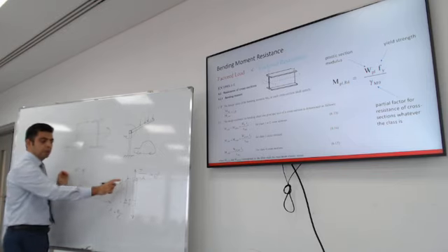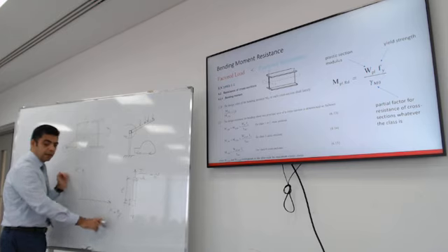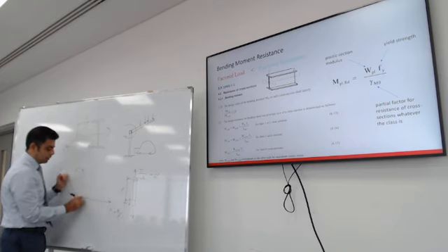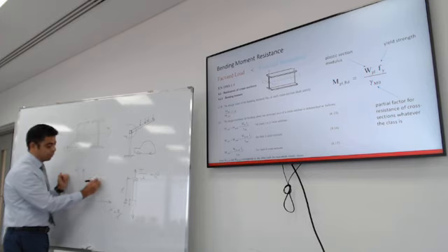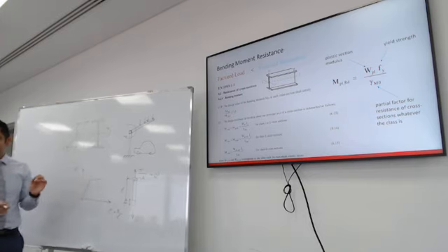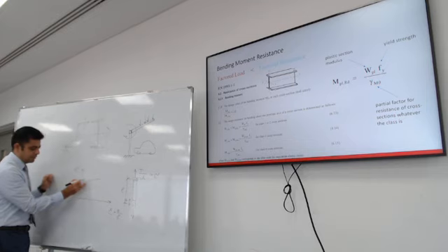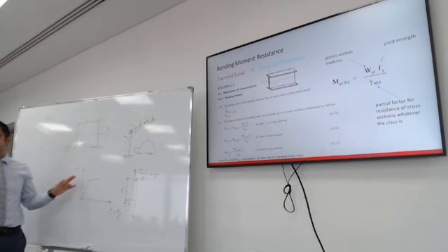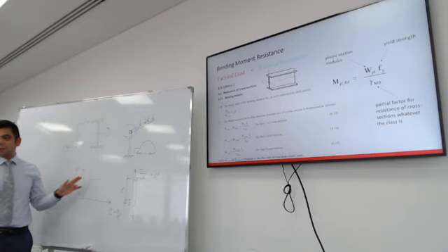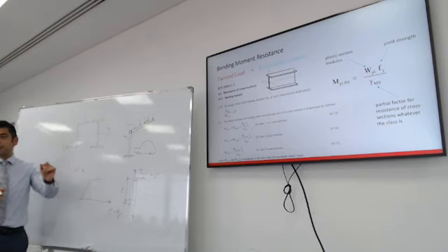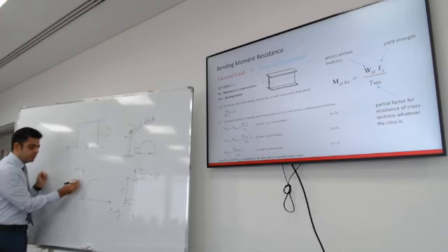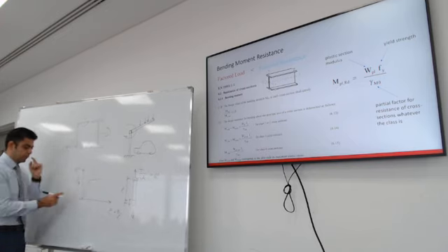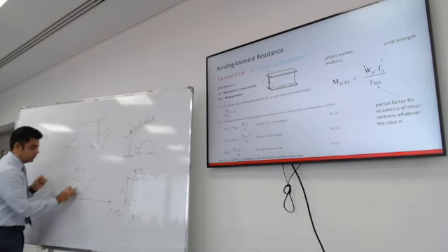The relationship between stress on steel and the elongation or the strain looks like this. It's linear, keeps on going linear until it reaches a certain stress, and then it cannot take load anymore. And then it pretty much fails. So how much is that stress? This is a number that the code will define. I will show you the tables that tell you how much is that load. This is called yield stress, or F yield. The yield stress.